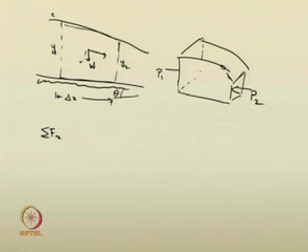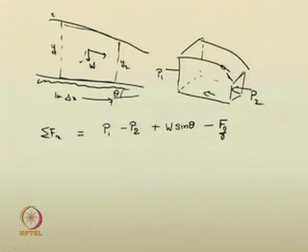So, now you can suggest that sigma Fx is equal to P1 minus P2, then the W acting vertically downwards. The component of that along the direction of the fluid flow is W sin theta, and another quantity, there will be frictional force on the bed, in this direction. Let me give this as Ff. So, this will be your equation for the net forces acting on the control volume.